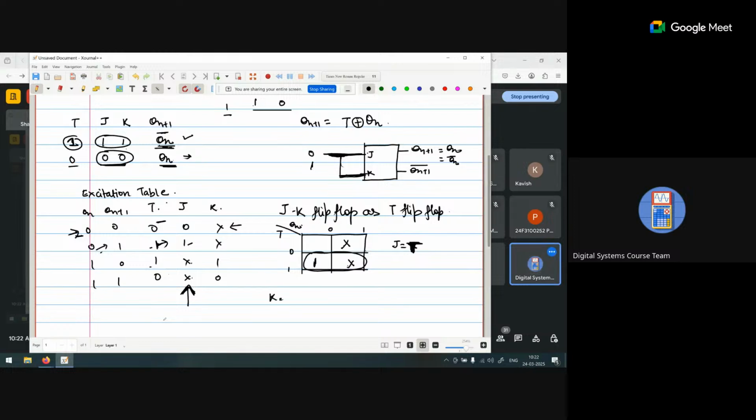Now what is K? So we go K map for K, T Q 0, 1, 0, 1. Now where is K? K is down here. T is 1, Q is 0, don't care. Now T is 1, Q is 1, here it is down here. So now we created a group here. Okay, so K is also T.